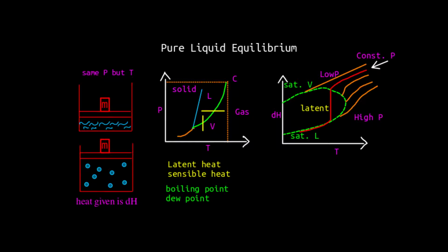And if we reduce the pressure or if we add slight heat, then the liquid is going to boil and evaporate. But here we are removing the heat, so the saturated liquid will cool along this path. So this also we can repeat at various pressures to find the loci of the saturated vapor and saturated liquid, and those two will intersect at the critical point, beyond which the gas state alone will exist. So we have plotted the pressure versus temperature as well as relative enthalpy versus temperature plots for pure water only.